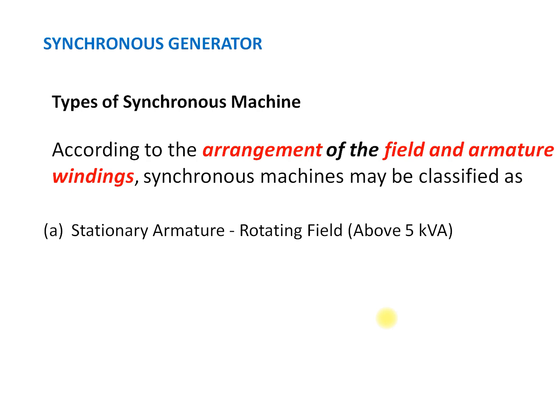the field. Either the field may be rotating, or the three-phase winding may be rotating. In either case, the DC field windings supply a magnetic field, which cuts those three-phase windings, and they will be supplied with EMFs, which are displaced in space and in time by 120 degrees. For this displacement only, the three-phase windings are wound.